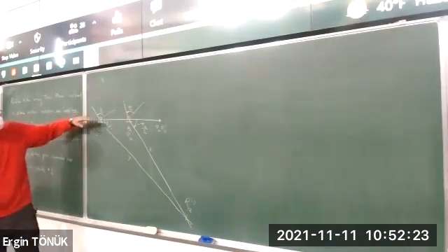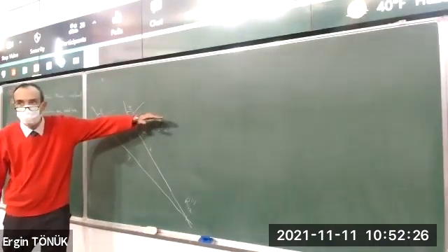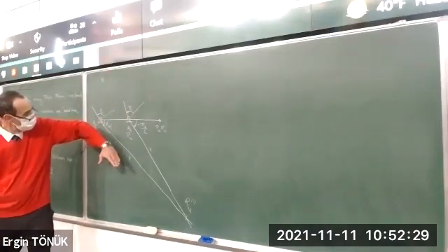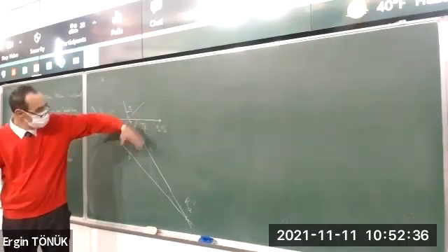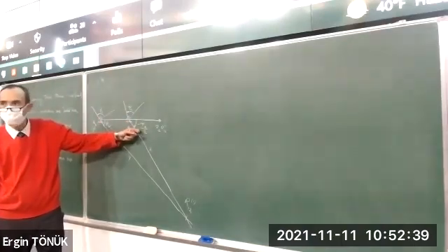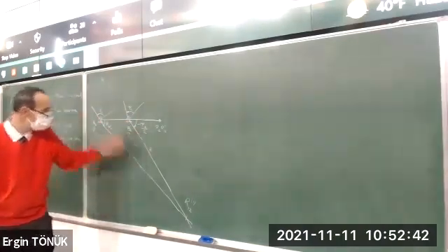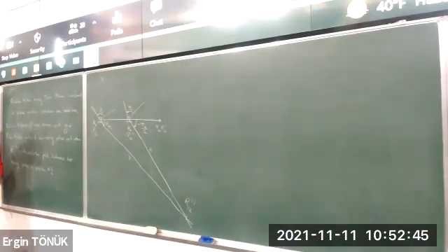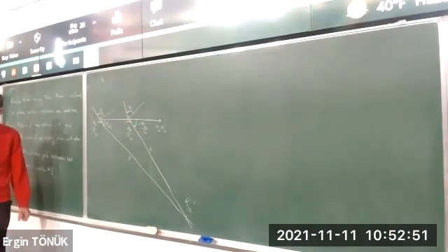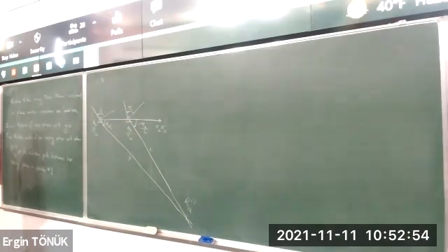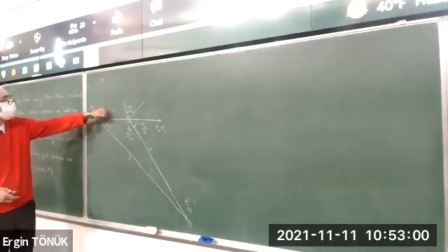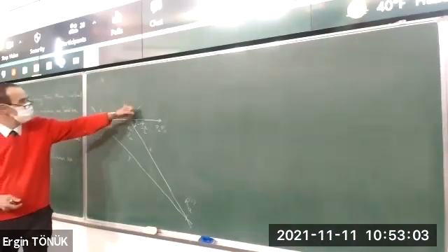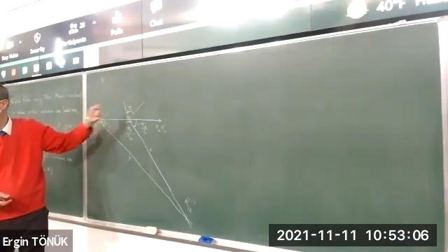Just take this as a directed line. And the angle between this line and line Y is negative half of this. And between this line and line X, negative half of that. Intersect them wherever it may be, down or up, depending on the angles. You find the relative pole. Now, using this relative pole, actually we will see 3 different methods to design a 4-bar such that when you rotate this phi1,2 amount, this is going to rotate psi1,2 amount. Okay?